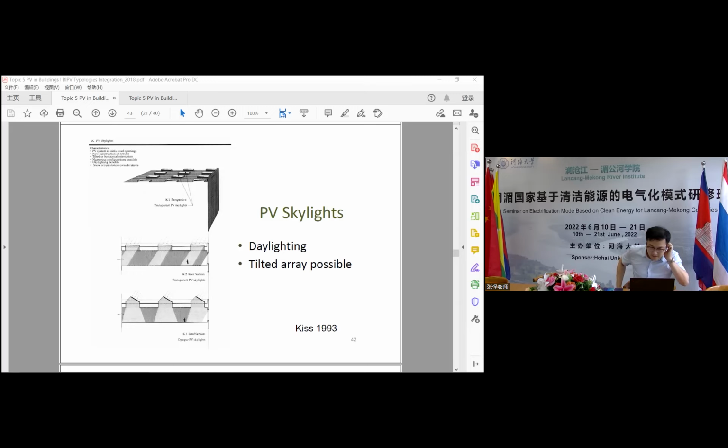It depends on the latitude of the location of the BIPV system. If the latitude is around 30, then the recommended inclination should be 30 plus or minus 2, which is 28 to 32 degrees. That should be the optimal tilt angle.